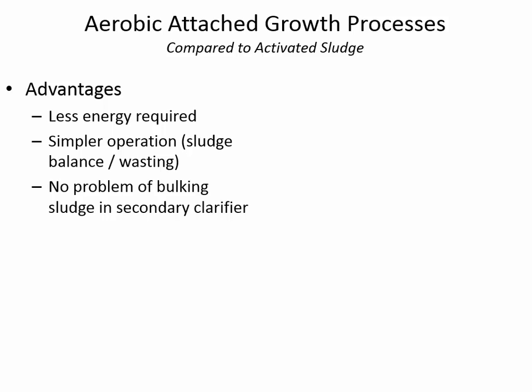In the case of attached growth, there isn't any recirculation of the sludge solids. The biofilm that sloughs off is just settled and the sludge is disposed of. There are a few rare instances where they do recirculate the biofilm, but in general, it makes it a lot simpler if you don't have to worry about balancing out sludge solids like you do in an aeration basin.